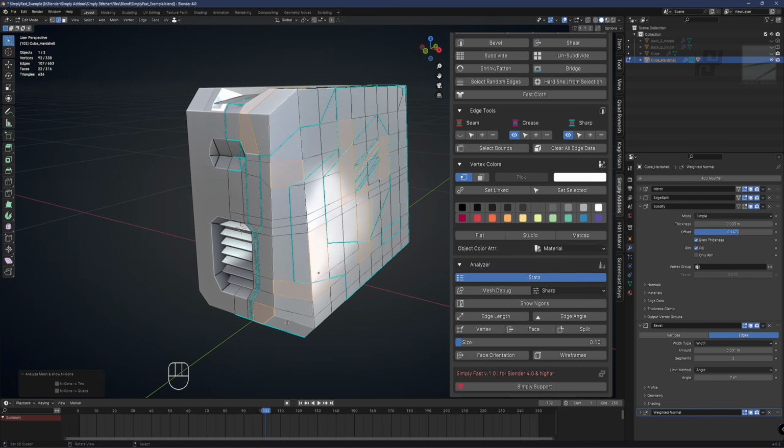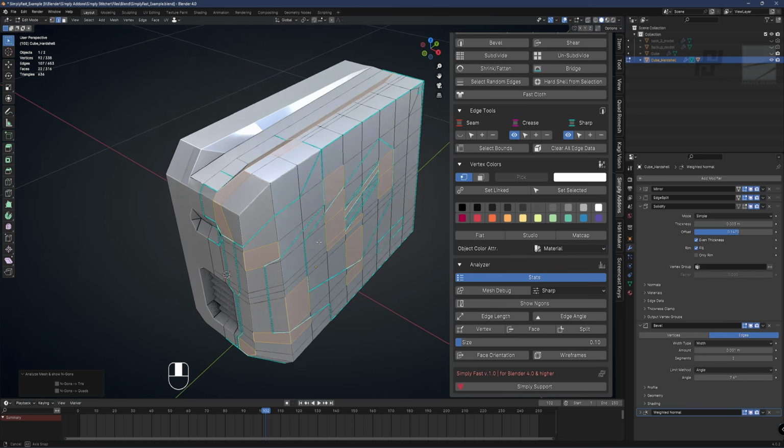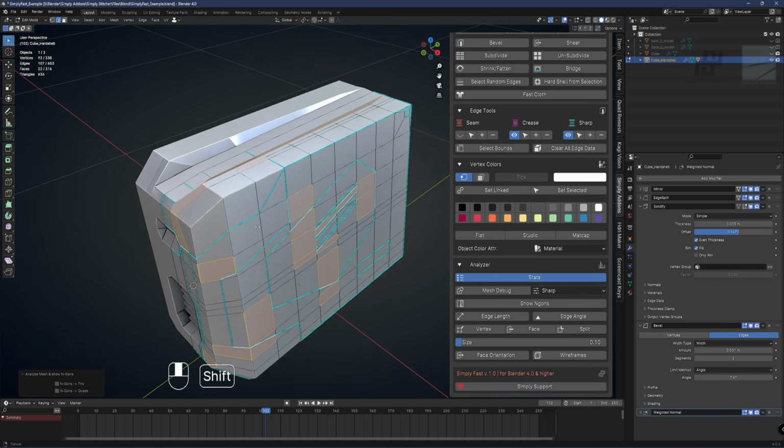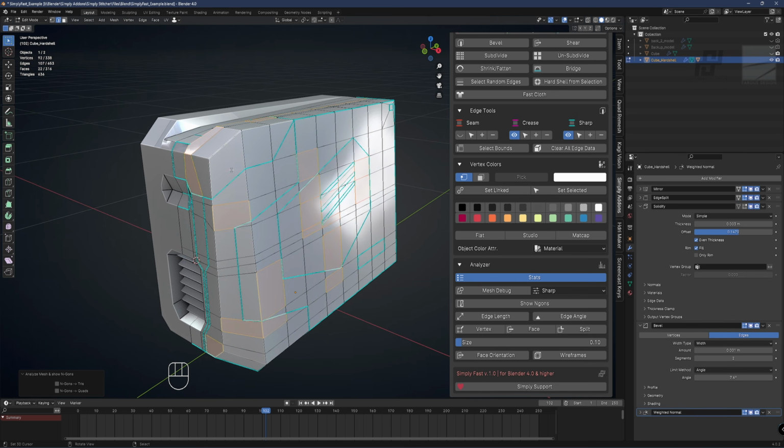Just hit OK, and then it shows all Add-ons. You can fix directly by hitting this button and make them quad. So depending on your needs, like for a game engine, it should be triangulated every time. Some people are struggling with the point, they're modeling, forget some Add-ons, and the engine cries and wants to have only triangles. And then this function will be helpful.